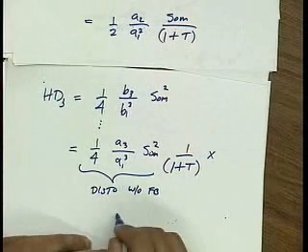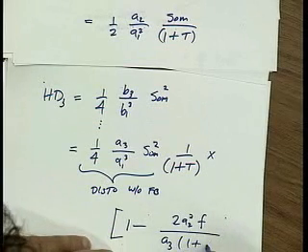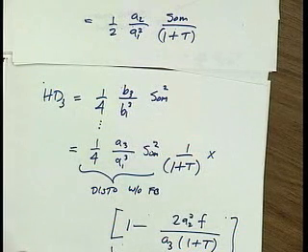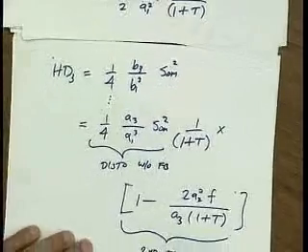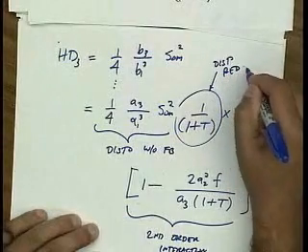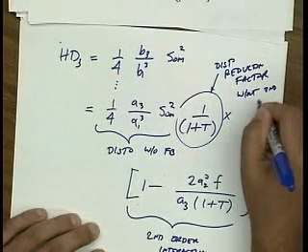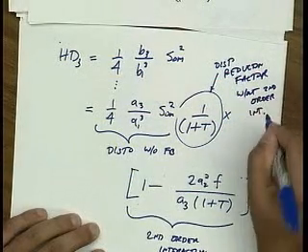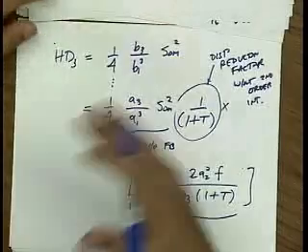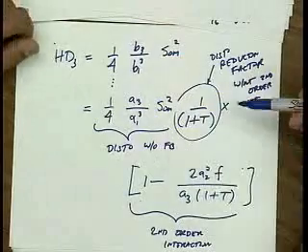So great, the distortion level is reduced by 1 plus t, but unfortunately I have second order interaction. So things are a little more complicated. So this is the distortion reduction without second order interaction. So what's happening is that the action of the feedback certainly reduces the third harmonic, but it also generates an additional third harmonic. Okay.